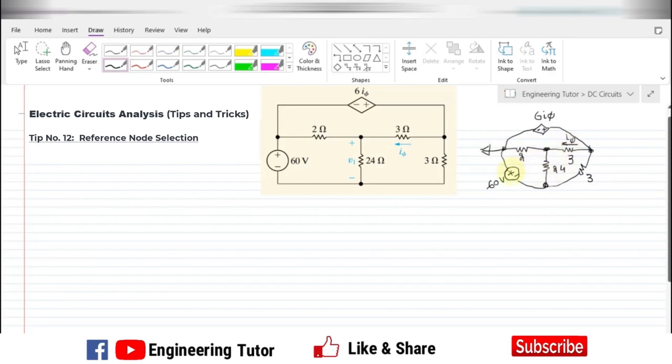It will simplify because now the two voltage sources will be in direct connection with this reference node. The first one is this one and the second one is this one. So the voltage here and the voltage here will be known. The voltage here will be minus 60 volts, and the voltage here will be 6I5. The voltages at these 2 points will be known, and we have to solve for this voltage only.